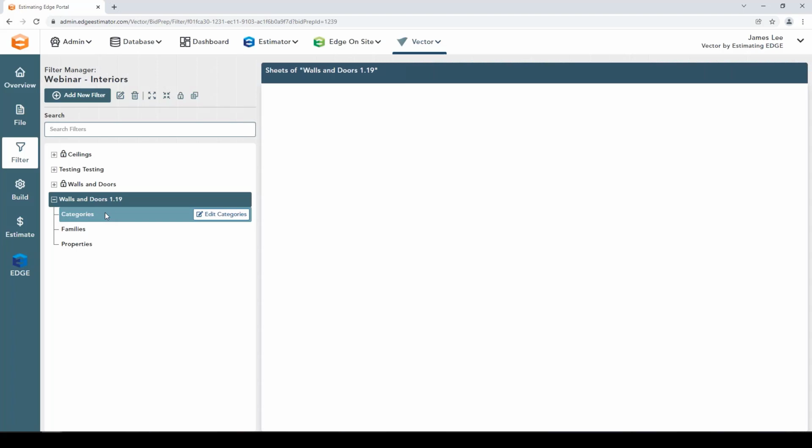Now, if you're familiar with Revit models, these terms you've likely heard before. If not, all they are different ways to identify data. Simply put, if you take a piece of data from a 3-dimensional model or a Revit file specifically, every piece of data belongs to a category, belongs to a family, and has its own set of properties. So what we're going to do today is say, hey, I'd like to bring in data from this category, but not that one. Or I'd like to bring in these families, but not those families. It's really as simple as that.